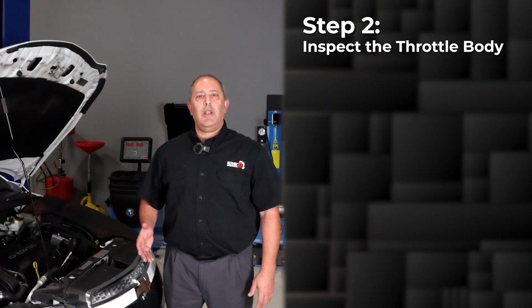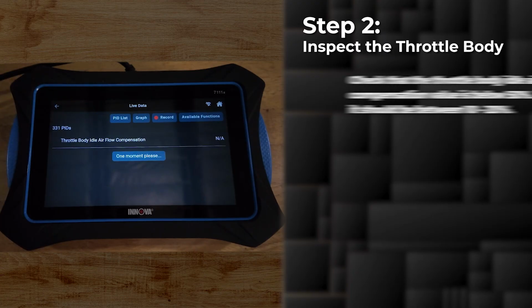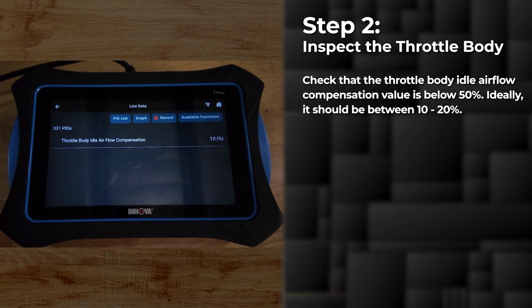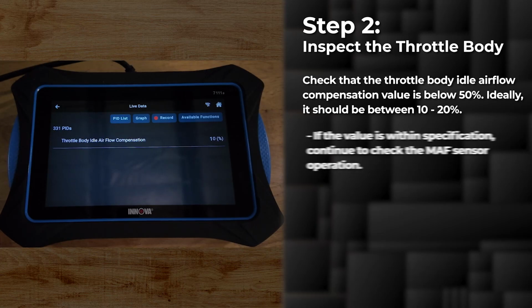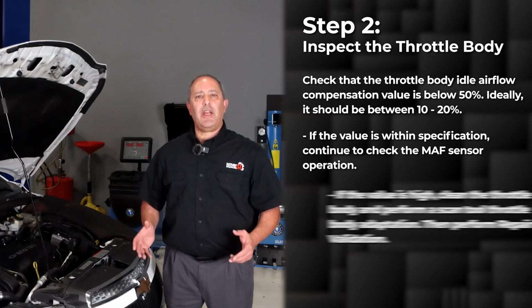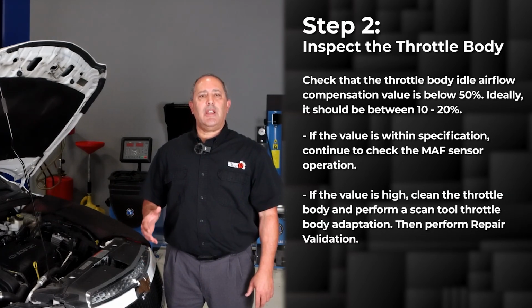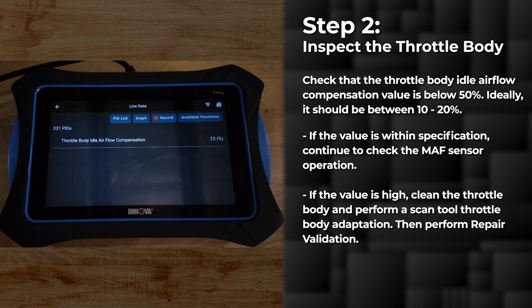Step 2. Inspect the throttle body by checking the idle airflow compensation value. It should be below 50%. Ideally, it should be between 10 and 20%. In this case, the value is within specification, so move on to the next step. However, if the value is high, clean the throttle body and perform a throttle body adaptation using a scan tool. Then perform the repair validation.